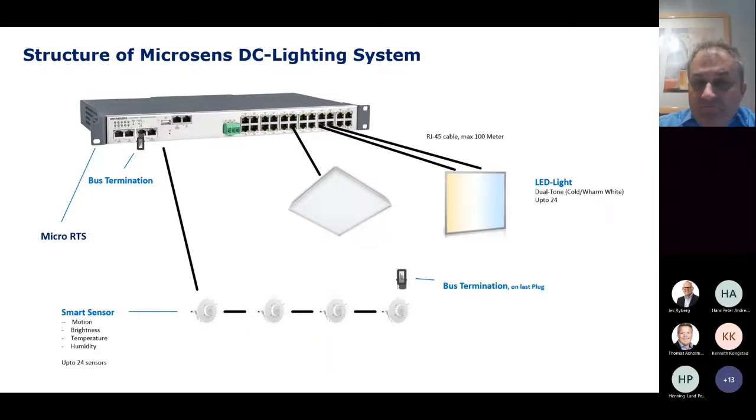So, the same preconditions we mentioned for the PoE apply: the luminaires connected to this smart controller or DC lighting system need to be naked LED arrays without an integrated driver.